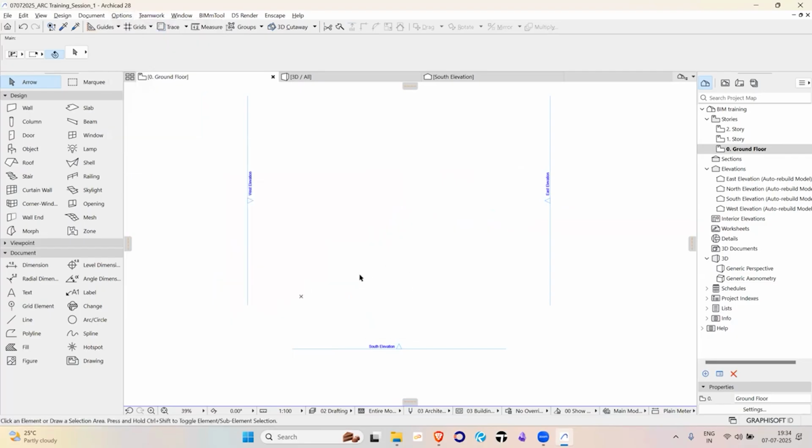I'll just turn it off and keep only this right now, so you cannot select it or edit it. It just stays there so that you will understand where it is created. And in terms of workflow, I will always suggest making the model very close to this point, because all the 3D based software or 2D software does the calculation from this origin point. So the further you go, the less precision it is going to have when it comes to many of the calculations. It tries to give the precision, but the closer it is, the better output it will give you. It's going to be the same for all the software. Everything is in the 3D space calculation. They do it from the zero point to the coordinate point.